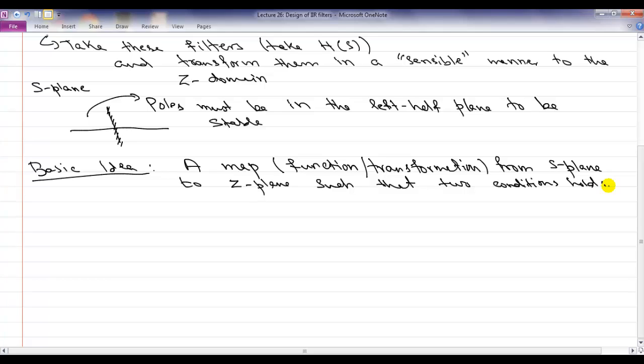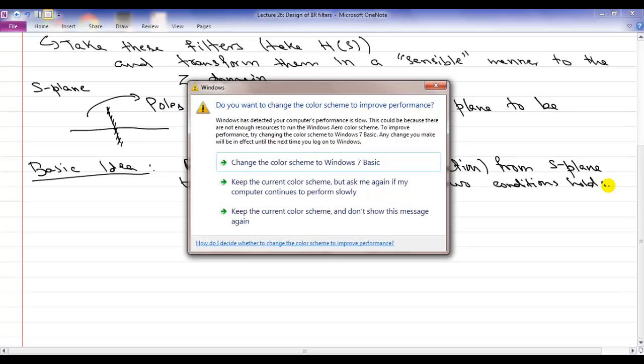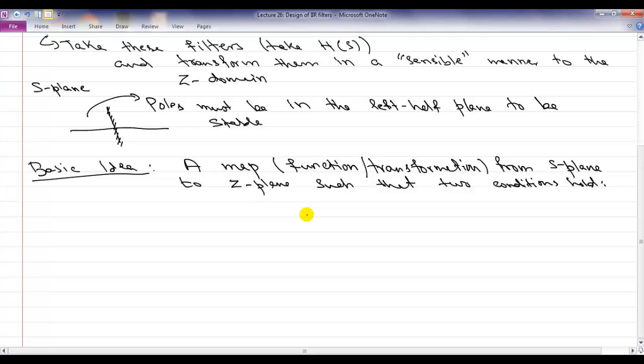And that's why you will somehow preserve the shape of your filter. If the idea is that low frequencies in the analog domain are kept and high frequencies get killed off, so you have a low pass filter in analog domain, you somehow need to map somewhat similarly. You can't map linearly, because in the analog domain your frequencies go from minus infinity to infinity, whereas in the discrete domain your frequencies go from minus pi to pi. But if you can somehow try to do this mapping in an intelligent fashion, you can preserve some shape of the analog filter in the discrete domain.